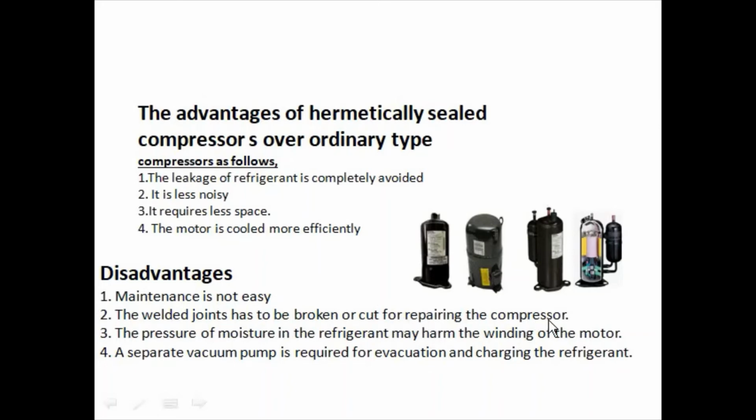Point 3, the presence of moisture in the refrigerant may harm the winding of the compressor during work. As you know, the compressor compresses refrigerant at high pressure and high temperature. During such compression, the moisture in the refrigerant may harm or damage the winding of the compressor.